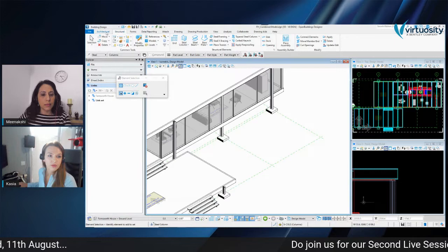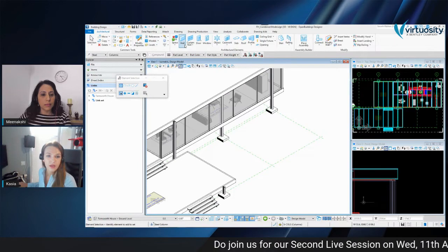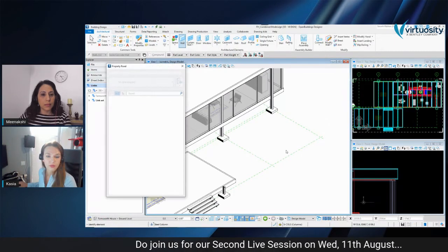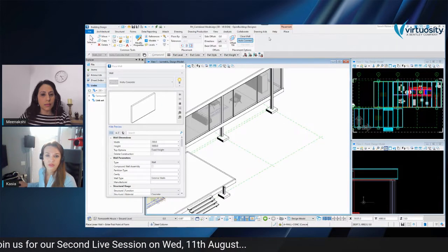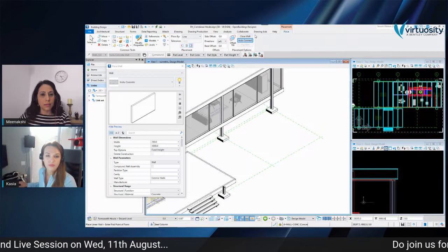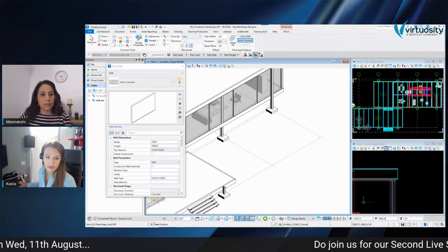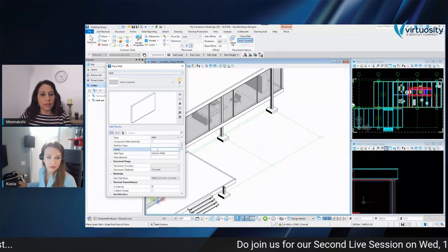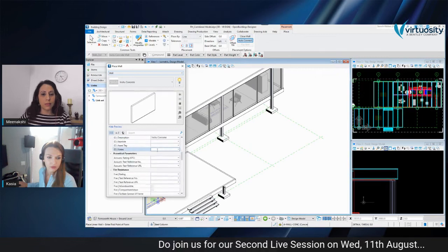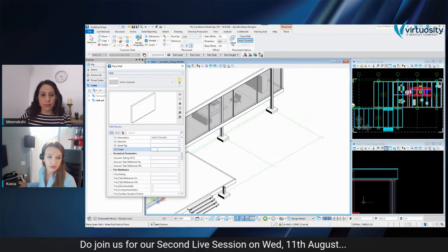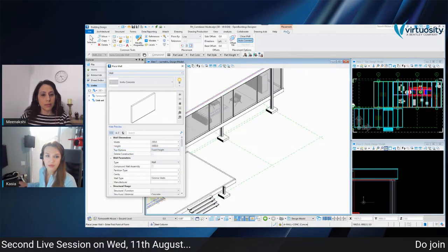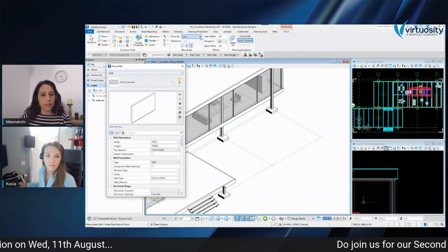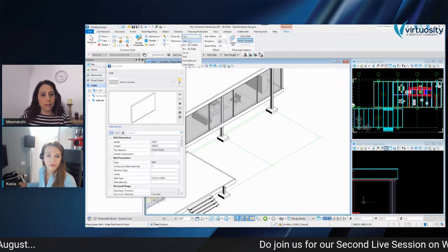And maybe as an example, I can also show the wall tool, just to show that there are always some different settings, for example, for the placement, but the general idea is the same. We have a look at the place wall dialog box. We set the data we want it to contain, and then we go to the placement tab where we set, for example, the placement method.